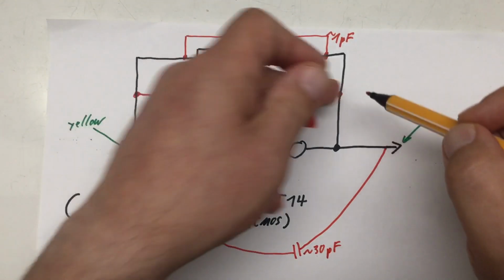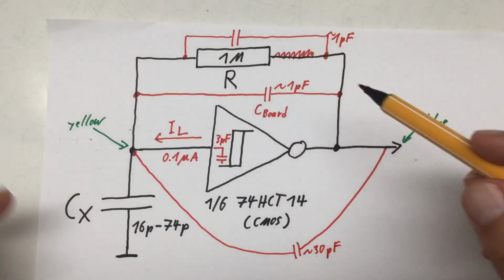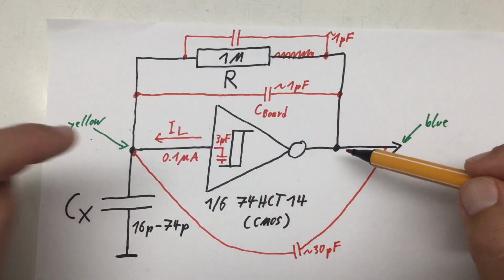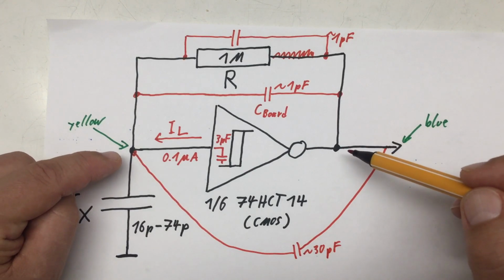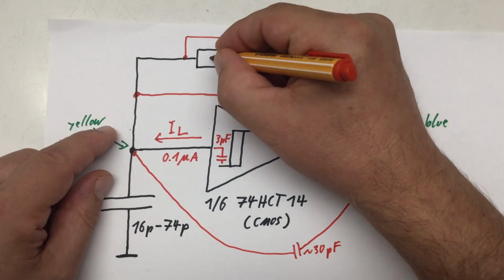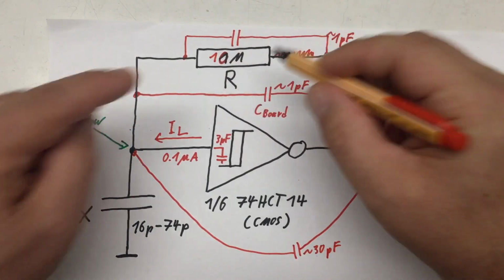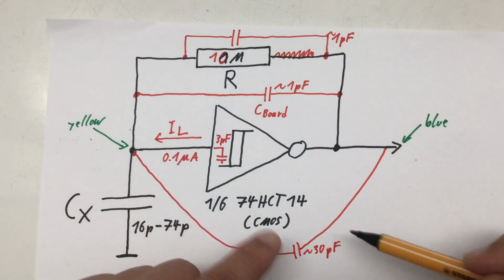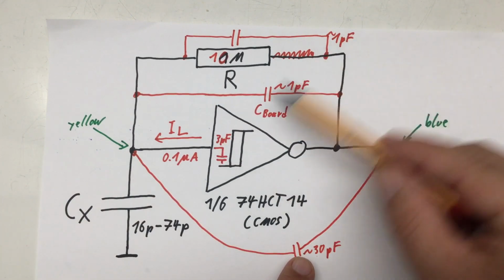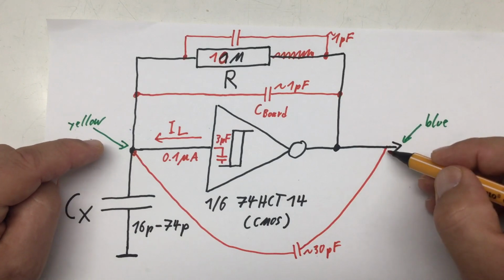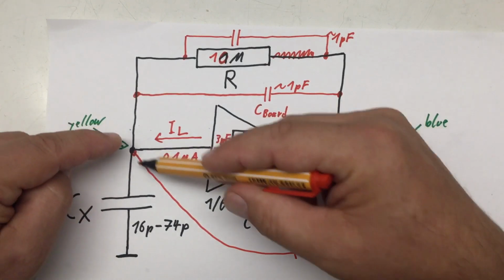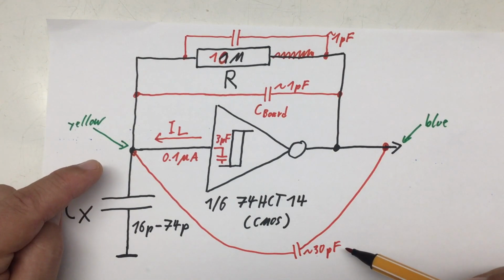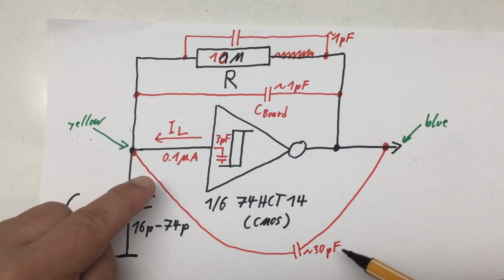Also shorting out, at least pulse-wise, when the polarity of the output changes, the output and the input. And by the way, we are here up at 10 megaohms. That was the last change I made in the previous video. And beforehand, we were talking about a few picofarads, and those oscilloscope probes added that parasitic capacitance of about 30 picofarads. And that's not all.